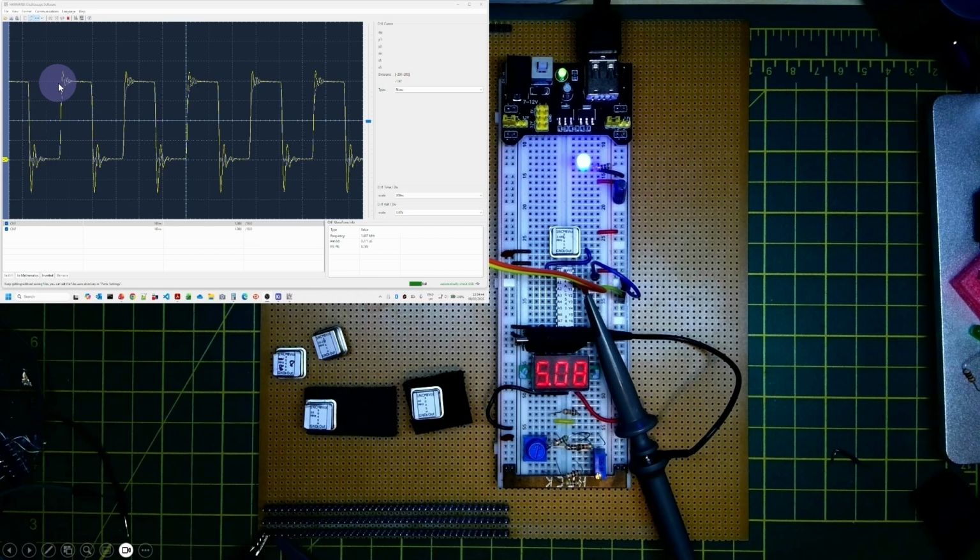And you can see on the oscilloscope trace here that we've got about a 3.6 megahertz signal here, but because of the electrical characteristics of the bus rail, so things like impedance and capacitance, we've got quite a lot of ringing here on the transition of the signals. And in particular, you can see here that from down the bottom here, we've got almost about a minus 1.7 volt sort of spike as the signal switches. And you can see this ringing, and also less so when it actually gets to the top here. So we're not going to look at solving that during this video. That will be coming in a couple of videos time.